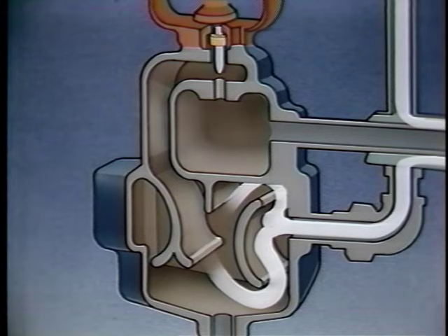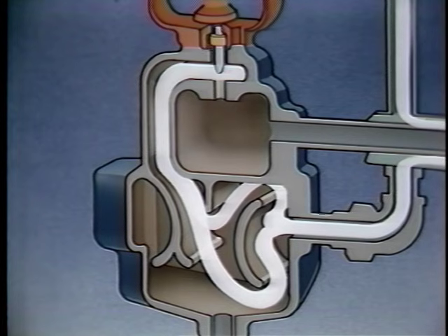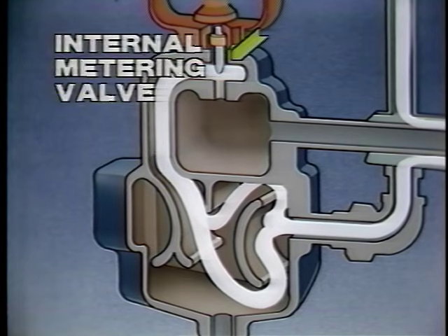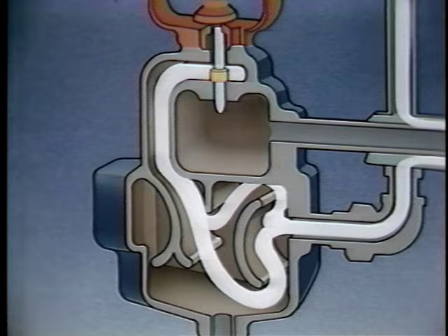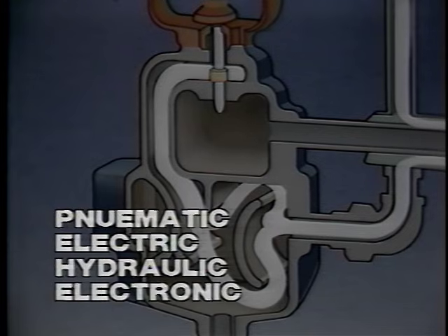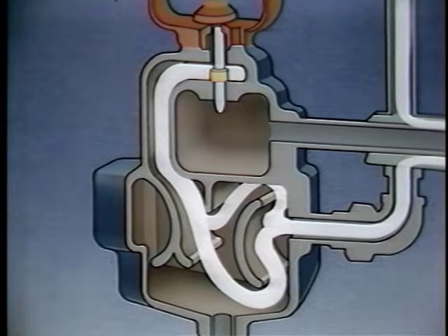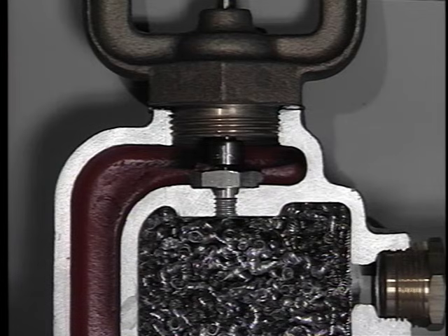After the condensate is removed, the conditioned steam is channeled to the top of the unit where it jackets the metering valve. The metering valves are made by Armstrong and installed as an integral part of the humidifier. Whether the valve operator is pneumatic, electric, hydraulic, or electronic, the same modulating characteristics, wide rangeability and interchangeability can be maintained for any orifice size. Additionally, if you need to change the operator of an existing unit for any reason, you can field retrofit the appropriate valve stem and seat assembly and never touch any plumbing.